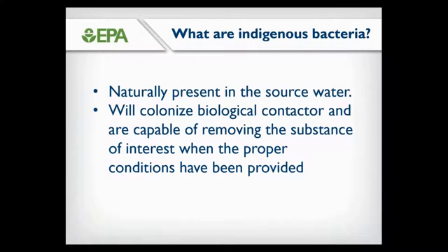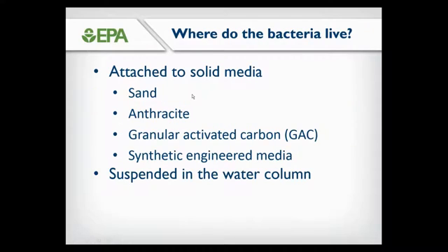What are indigenous bacteria? We're defining indigenous bacteria as bacteria that are naturally present in the source water, and they're being allowed to colonize the biological contactor without any additional enrichment, and are capable of removing the substance of interest when the proper conditions for their growth and maintenance have been provided.